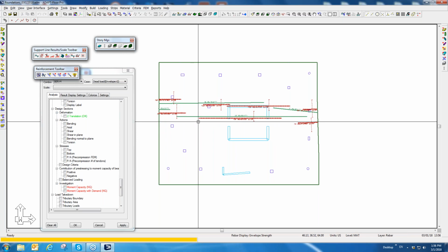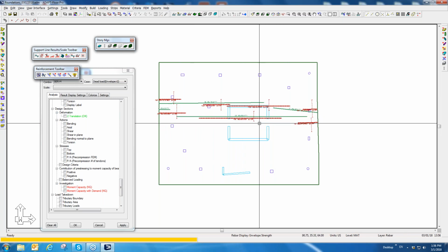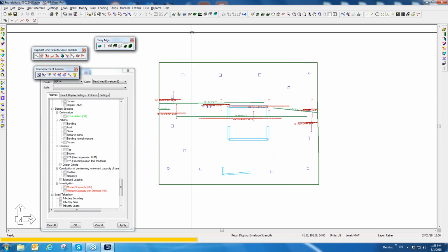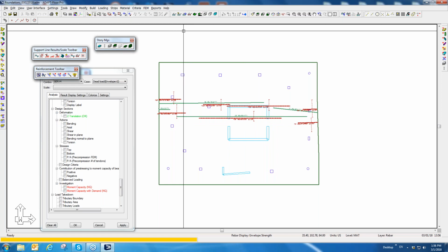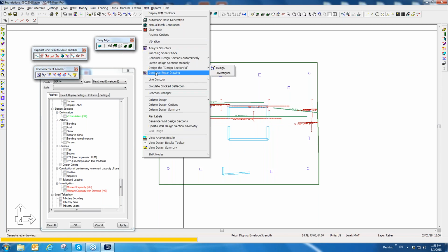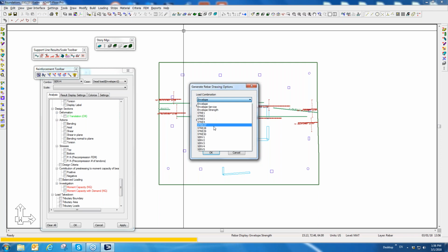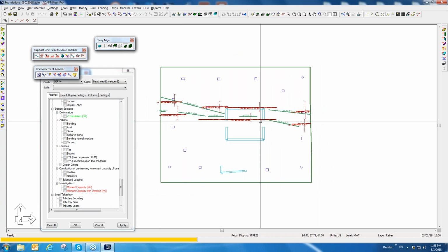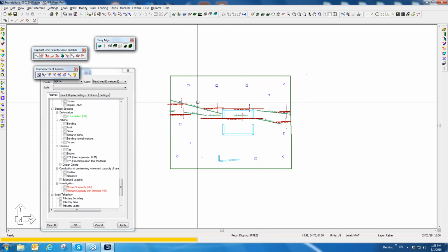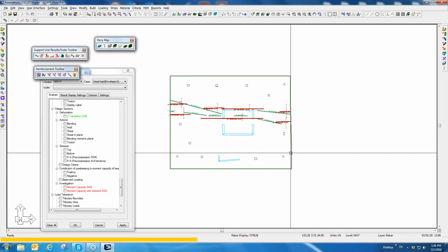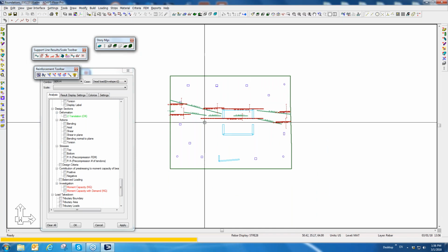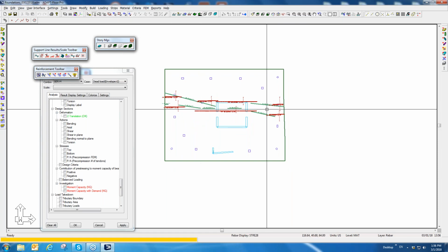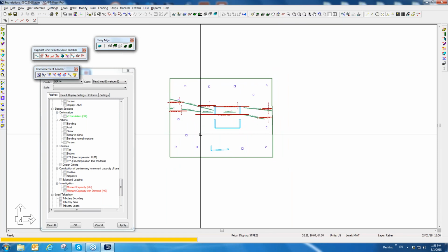So you might have demand at certain locations for different combinations, but when I envelope it, it's just going to chain those bars together if they overlap individually, if we looked at the individual combos. So I'll go back here and pull up one strength combo, for example. We get something like this. So the program can produce those reinforcement results. If I had designed all the sections, then obviously we would have reinforcement for the entire mat. In this case, we've only produced it for two design strips.